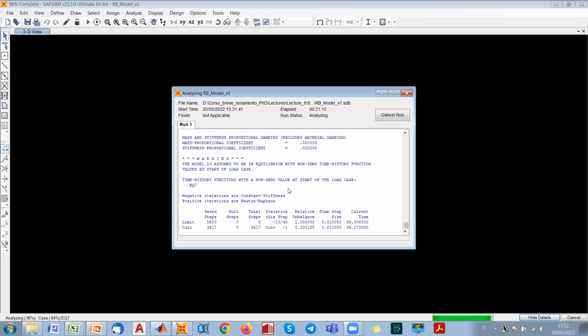And for lead rubber bearings, the recentering behavior, even if it is very small, is provided by the rubber compound, exactly as for the rubber bearing. And it is actually modeled as a linear behavior. And also for the curved surface sliders, the spherical shape of the sliding surfaces just leads to a stepwise projection of the applied vertical load, which is modeled through a linear function.